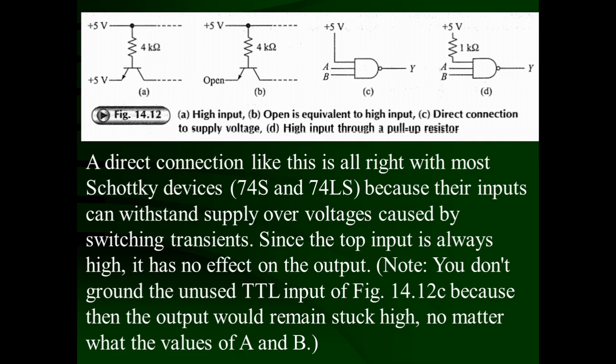Second question, can we connect this unused input to the ground? Yes, if it is a NOR gate, the unused input should be connected to the ground. Otherwise, if it is connected to the VCC, then output will be stuck to the high in case of the NOR gate, and in case of this NAND gate, if this unused input is connected instead of plus 5 volt, it is connected to the ground, then one of the input is low, then output of the NAND gate is going to be definitely high. So it does not bother about A and B. So real inputs have no control over the output. It is stuck to the high.